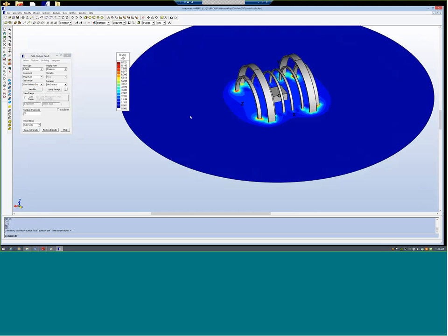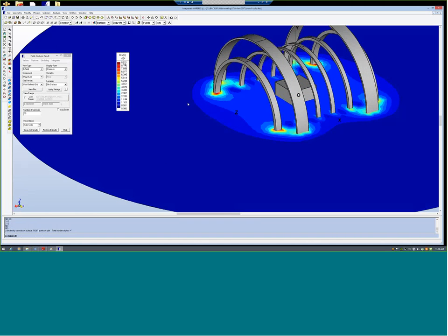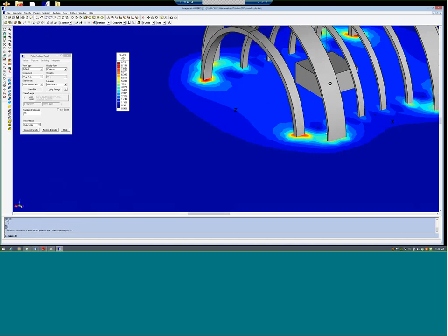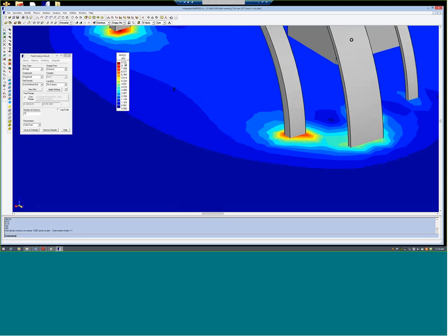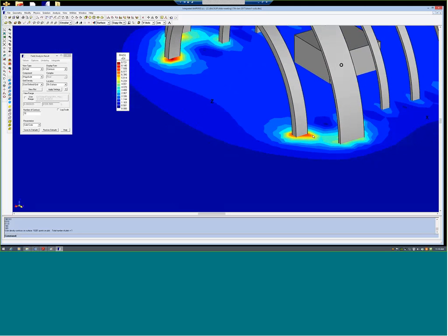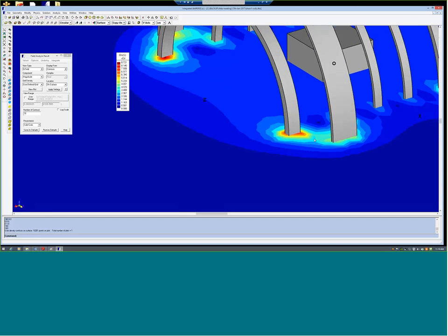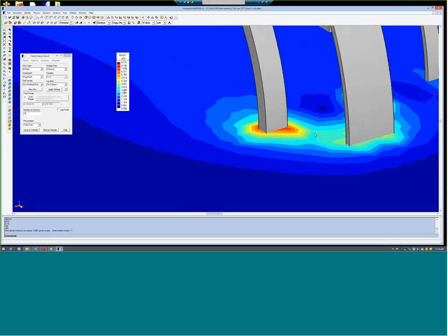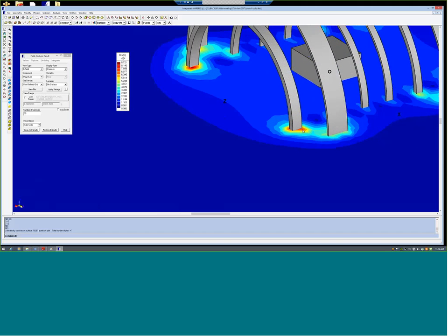Now you see here, it looks like between these two coils the field is going as high as 8.7 Tesla. So 1.5 Tesla only within that 1 cubic foot volume, but the fields inside here, in this cyan color, go all the way to 3.5 Tesla. And near this coil, it has got 8.7 Tesla.